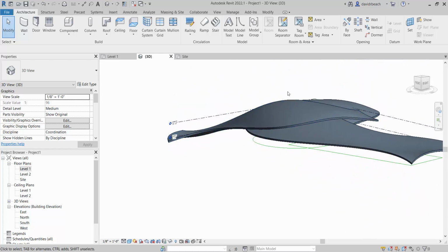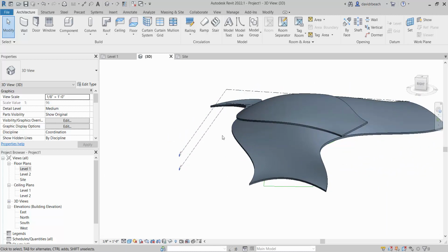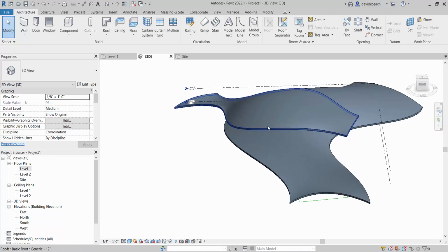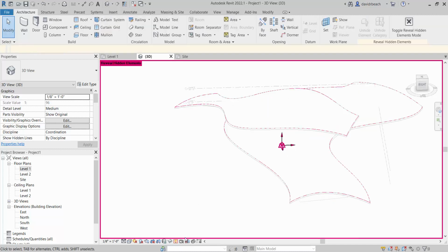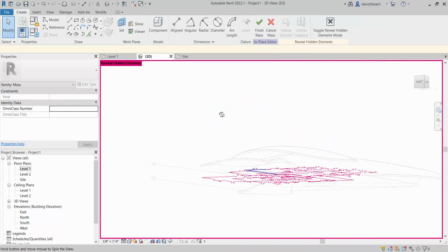I'm going to increase that slope and sweep to provide a little additional separation between those 2 roof forms. To do that, first I need to unhide that overall massing form. So I'm going to select my light bulb, select the top massing object, and go edit in place.